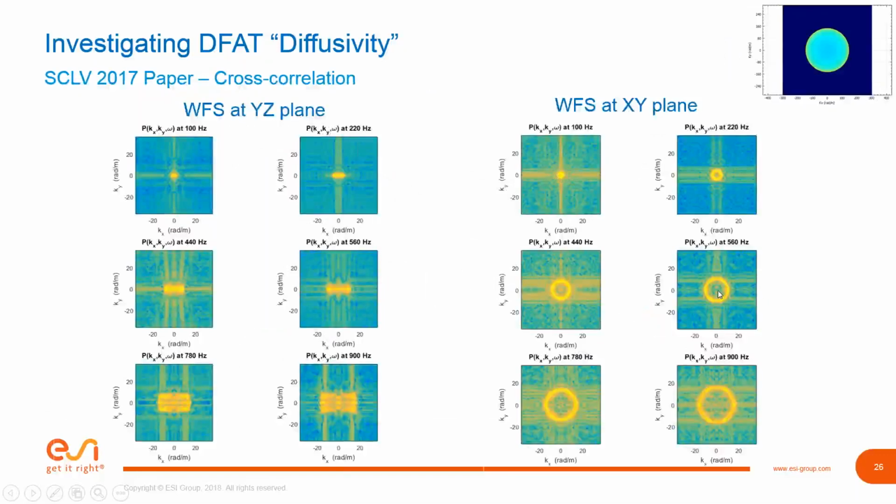and you can see that by looking at the wave number frequency transform on the right in a plane that's also perpendicular to the ground. It does look diffuse. You see the ring at the different frequencies. A couple hot spots, a couple relatively colder spots, but it looks like a ring. That means it's diffuse. That means it looks like and is equivalent to a reverberant test chamber. On the left, that's parallel to the ground. You see it only looks like a ring in one direction. It isn't diffuse. You need to change your speaker correlation, rerun it, or explore changing the geometry and angles of some of those faces if you want to get it diffuse.